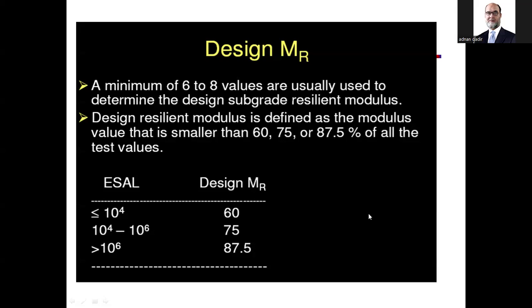Then comes another thing, and it's very important that you must use this. Generally, roads are built over kilometers and kilometers. So testing a soil at one point is not good. You have to have soil tests along the different stations, and then you draw a graph, and from that graph you will find the best representative value of CBR.